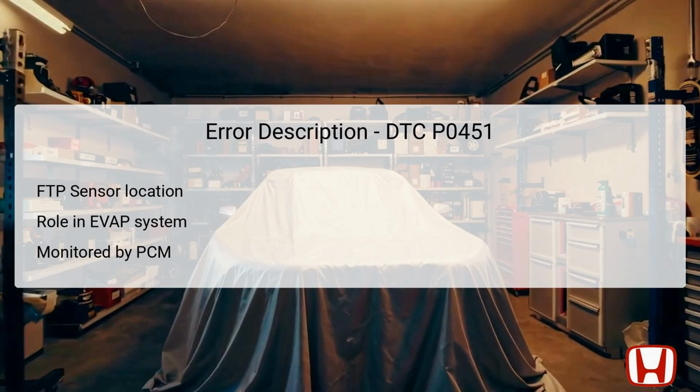Specifically, as fuel tank pressure increases, the FTP sensor outputs a higher voltage signal. Conversely, when the pressure decreases, the output voltage drops accordingly. This dynamic allows the PCM to determine the overall health of the EVAP system, ensuring it functions correctly. If the PCM detects an inconsistency in the signals, like abnormal voltage caused by electrical noise, this can lead to the storing of DTC P0451, indicating a trouble in the FTP sensor's range and performance.